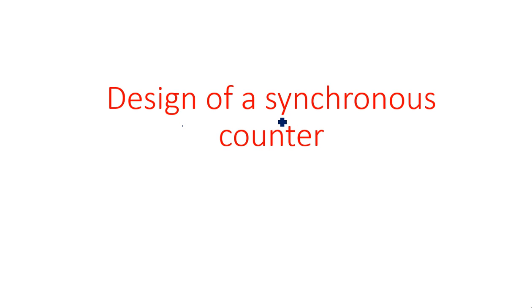Hi everyone. In this video, I'm going to explain a synchronous counter design. A synchronous counter design is quite different and difficult compared to an asynchronous counter. In an asynchronous counter, all the flip-flops are T flip-flops, and we don't have any logic circuit at the inputs of the flip-flops. Whereas in a synchronous counter, we should have a lot of logic circuitry involved